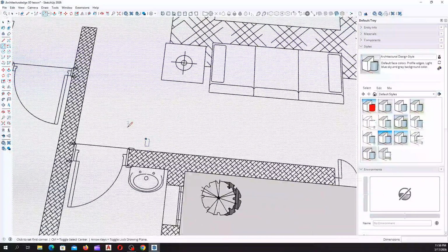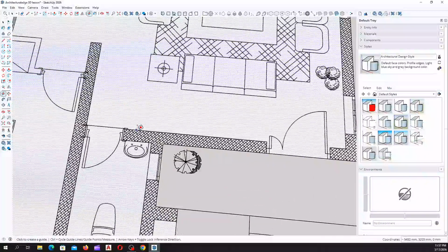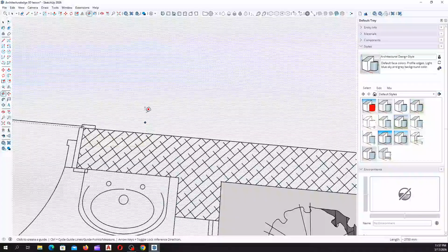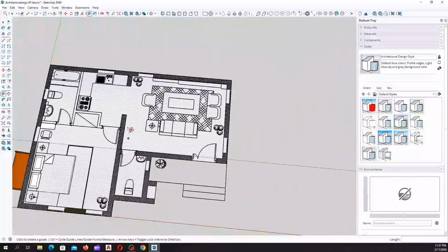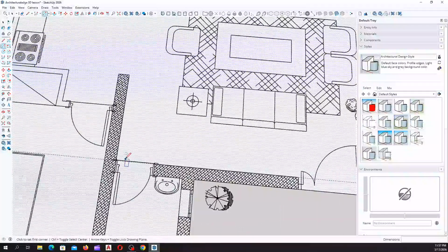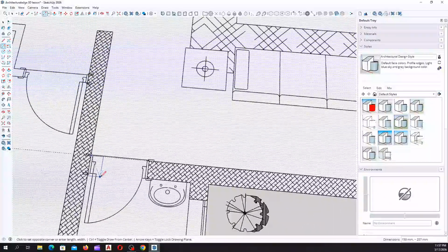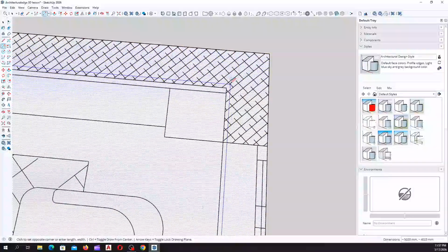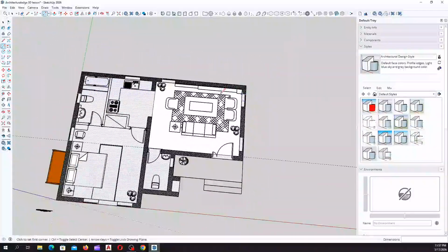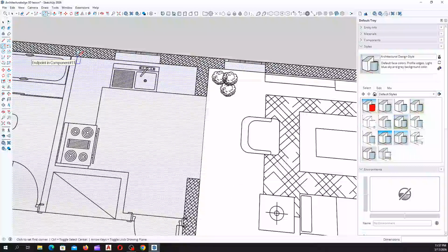So what we move into next, we'll pick our right angle tool. Then let's start from our living room. Before then, we'll have to use our tape measure, so our tape can serve as a guide. We'll put our tape on this point. Then you come to your right angle tool. You can pick from the point your tape intersects with this wall, then we'll snap to this wall. Now we are trying to create a segment between our wall and our living areas, that is our interior spaces.